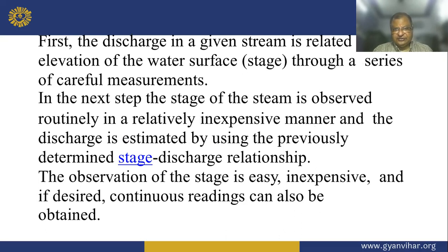First, the discharge in a stream is related to the elevation of the water surface, through a series of careful measurements. The stage of the stream is observed, and the discharge is estimated by using a previously established relationship.